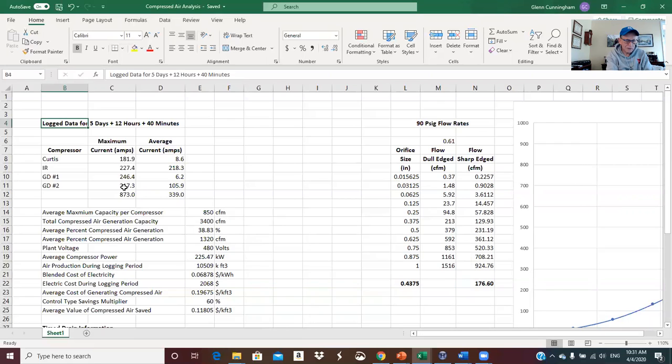At least what's being blown through these 4 traps, and the economics are good because you're going to basically get rid of 4 time drain traps with 1 zero loss trap. Well, that's 4 to 1 bang for the buck. That's pretty good. Now they have some other traps which they probably ought to get rid of, and I think what I would do is write up the 1 to get rid of the 4, and just say in there they should probably remove the other traps as well. I'm not sure how many total they have.